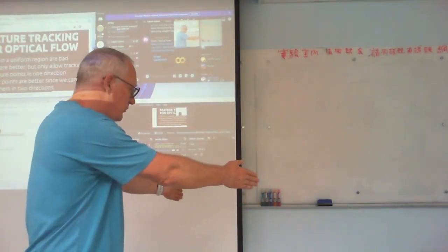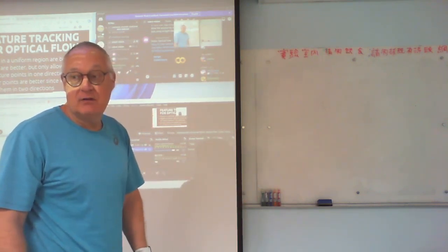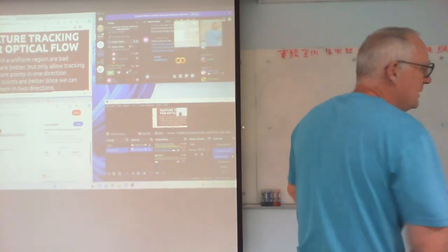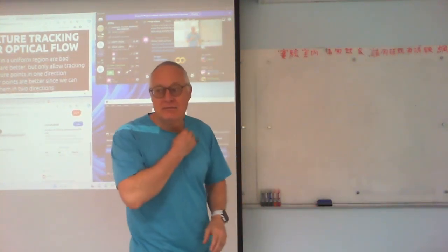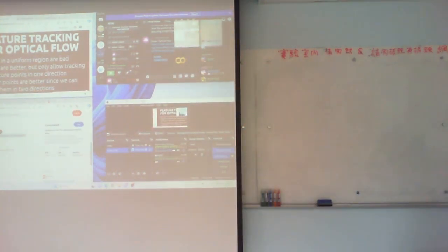But if this is my field of view and I don't have the grids on the floor, then I get the same image independently of how far I move along the line. So we cannot measure movement along the line, but off the line, like closer to the line or further away, or rotations, relative orientation towards the line, we can measure quite nicely.